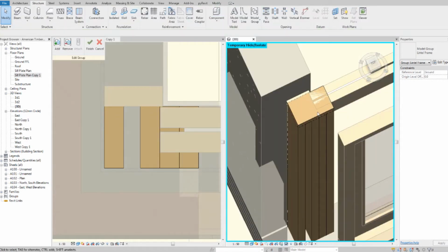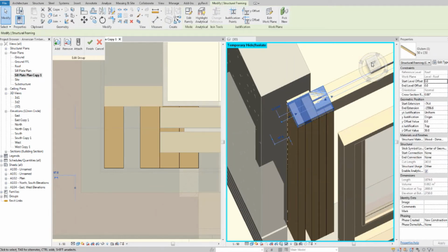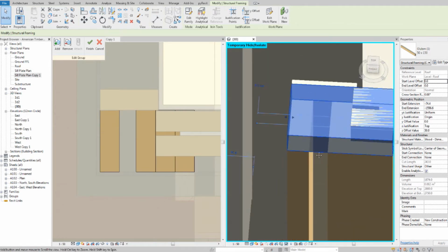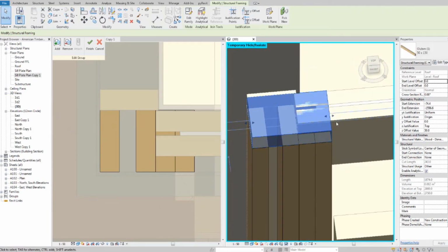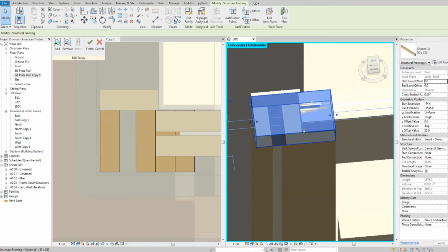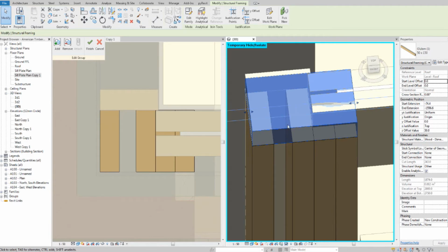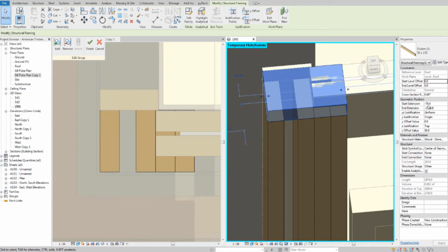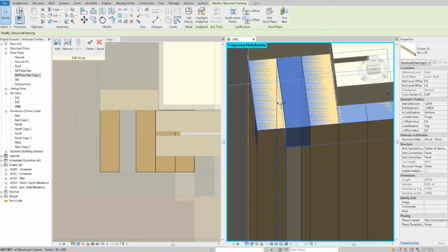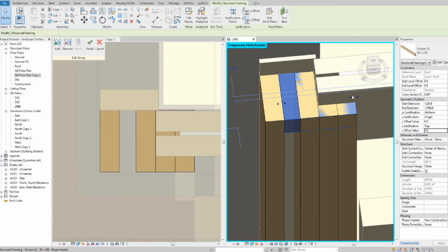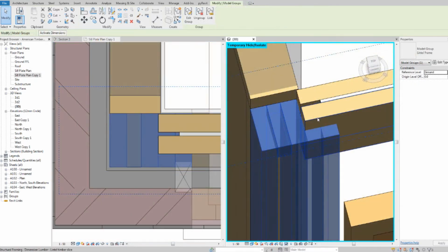I'm editing this and I'm going to pull this back. If there was another stud in the middle here, I could have had this head rail sitting on both studs while the lintel can sit on these three. But I can't have a head rail like that. So what I'm gonna do is drop this by 50 so it acts as a noggin. Pull this back and I'm pulling this back here. So I'm gonna pull these into here and put another head plate up here.